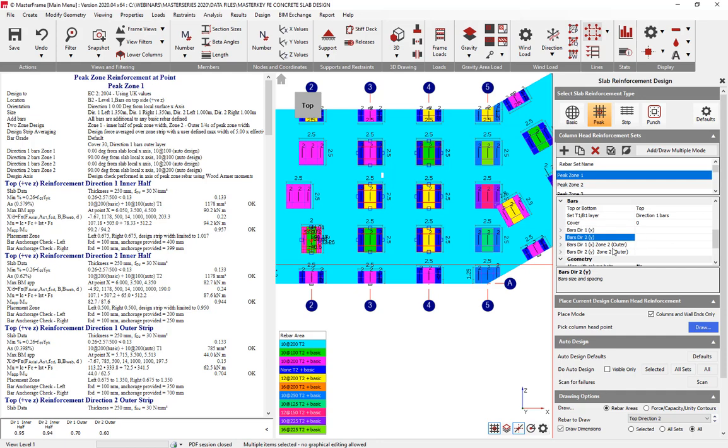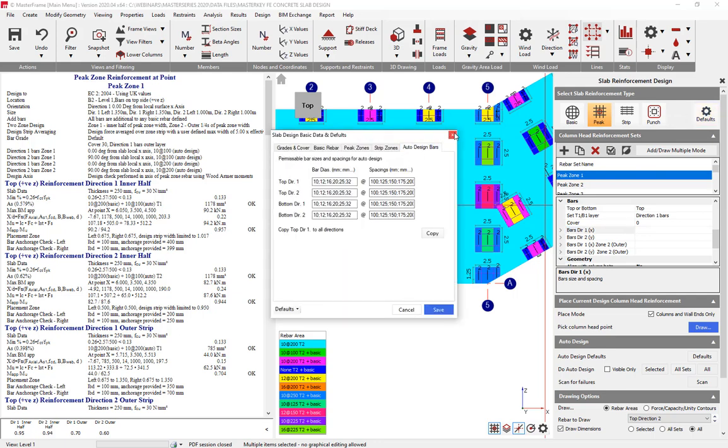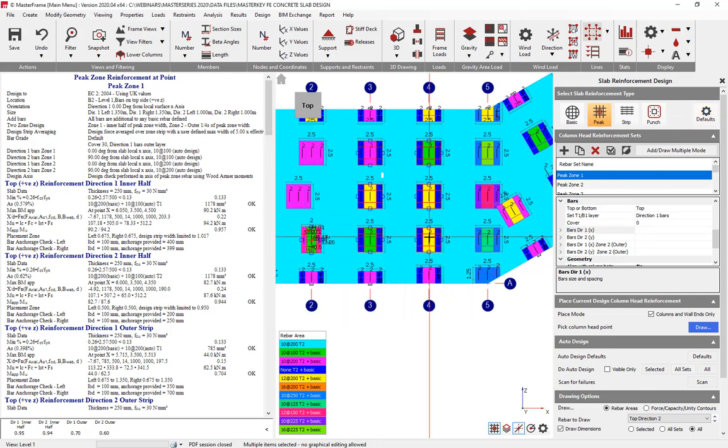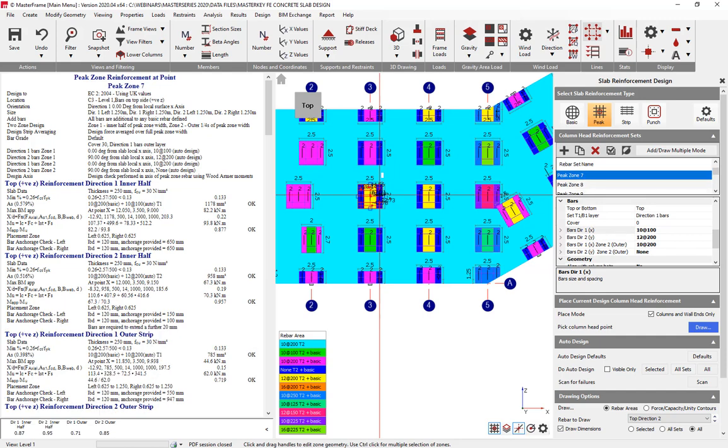Another strategy at this point might be having allowed the program to auto design with a wide range of selection of rebar, because remember the selection comes from what we determined in the auto design scope here. We could modify that scope, and for instance, looking at this, let me just see if I can determine anything that's a little bit more unusual. You know, I've got T10 at 200s, T10 at 100s there, which does seem absolutely fine.